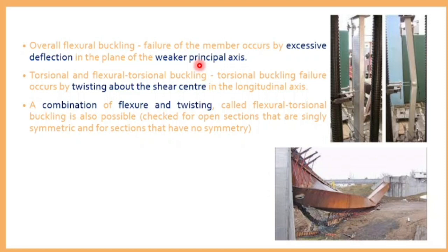That is why in all the monument structures, whatever you see, it might be a mosque, it might be a large palace, you can see circular columns. Why they prefer it is, they have equal moment of inertia on all the sides. If you try to push in any direction of a circle, it provides the same resistance. So that is why they provide a circular section. But now, why are we reducing the circular column? It is more work. It is not easy to do plastering for a circular column. Due to work and time, they are making rectangular or square columns.